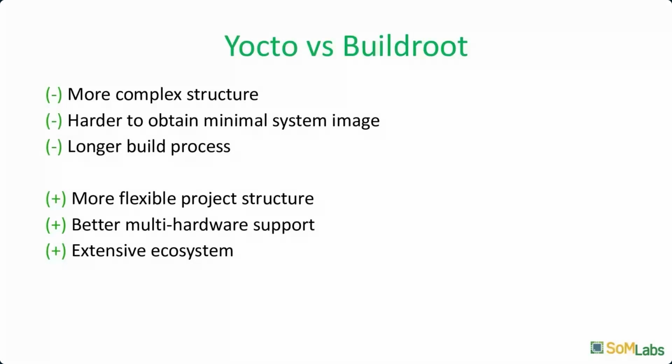And also it has a great ecosystem, with packages and software tools provided by different companies and communities. And I have the impression that the scale of the ecosystem of Yocto is wider, and it's easier to find ready solutions to include in Yocto than in Buildroot. However, it also depends on experience and requirements for a particular project to choose between Yocto and Buildroot. Both of them are frameworks designed for use in embedded systems.